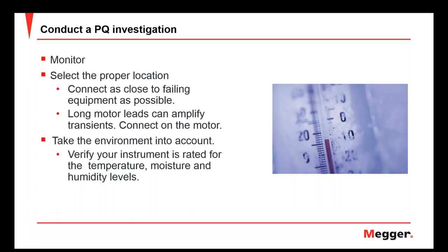Now, we're going to want to hook a monitor to it. The first thing is we need to select a location. Where are you going to connect it? Well, if you're troubleshooting a piece of equipment that's tripping offline, or a particular piece of equipment is having a problem, a motor not coming up to full power, you want to try to get as close to that piece of equipment as possible so you can see what voltage and current that particular equipment is seeing. The further away you get from it, the less representative it is. So we want to get as close as we can.